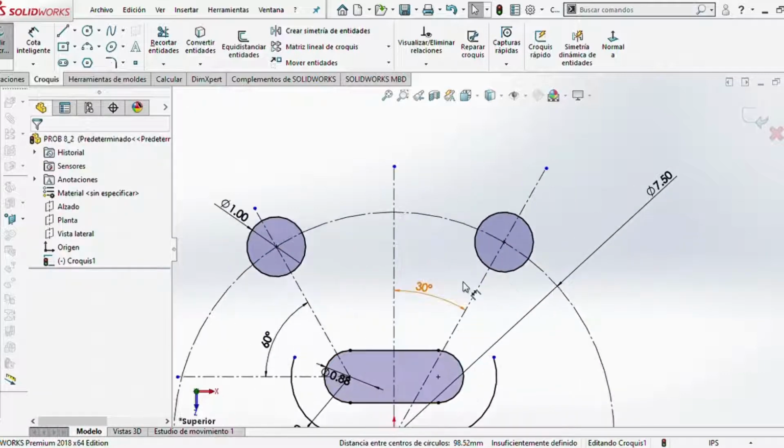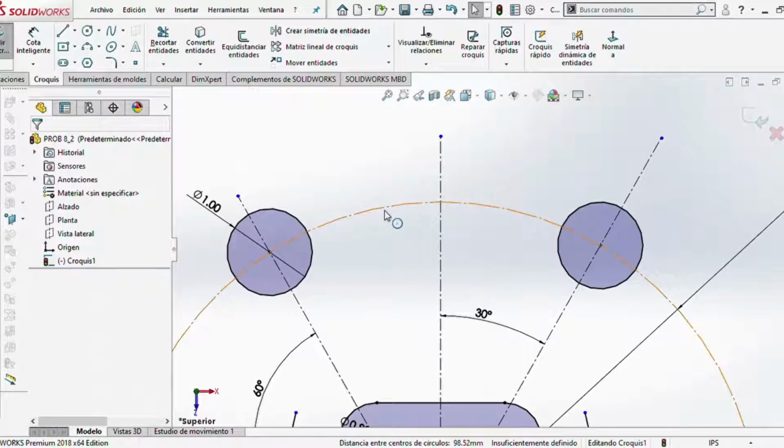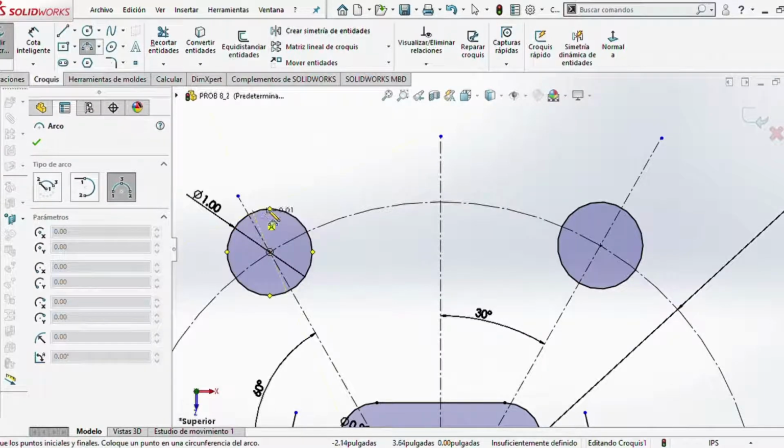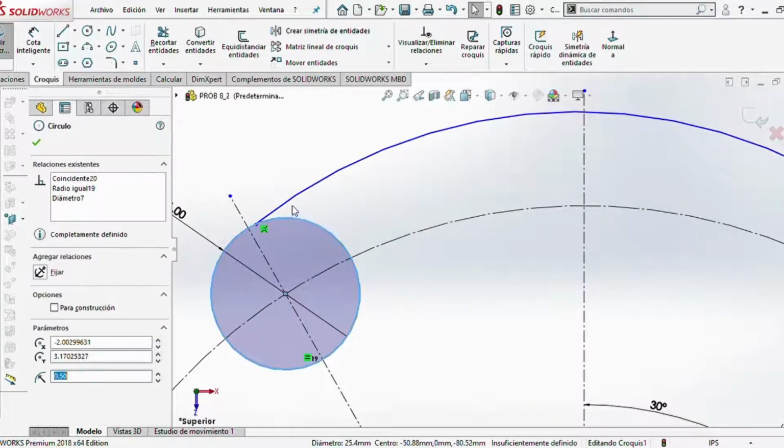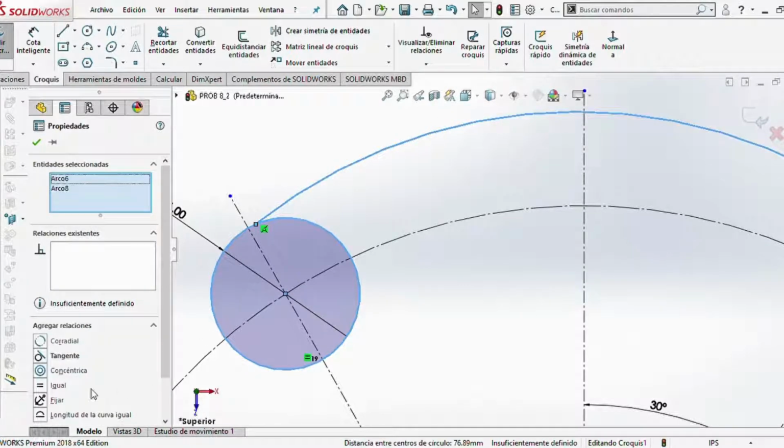There we have it. The next thing that we have to do is we have two options to draw an arc, a 3-point arc, or to use this special tool. But in this case, we're going to use an arc. Make sure it's coincident on this side. It doesn't really matter for now. Just going to be the measurement of that line.